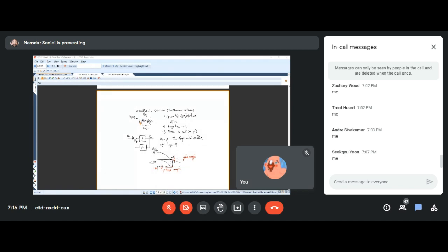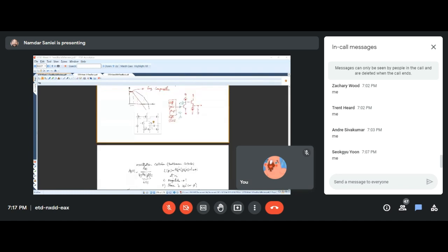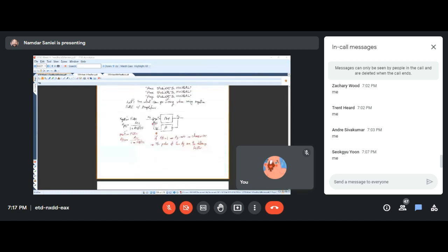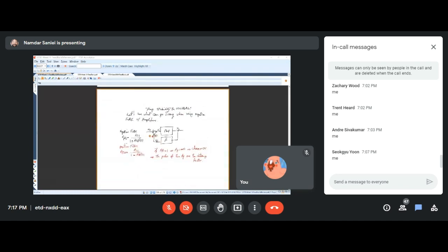How was the phase causing negative here? If you go back to this original thing, we had a positive. Positive means no phase difference. So it means that around this loop, all the signal is having the same phase. Same phase means either 0 degrees or 360 degrees.